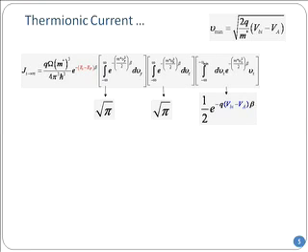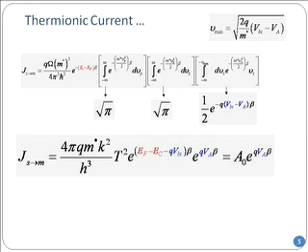I will put it in as the top limit, and once I have done that, if I do this integral, I will pull back out this, the limit will come here in the exponential, and then that will be the final answer. So once I pull all those extra factors down, this is the final result. The final result has a bunch of constants, goes as T squared, EC minus EF, VBI, and you can see I can put all those prefactors up front as A naught and q VBI, q VA divided by kT. Very similar to the PN junction flux, you see, exponentially increases with applied bias.